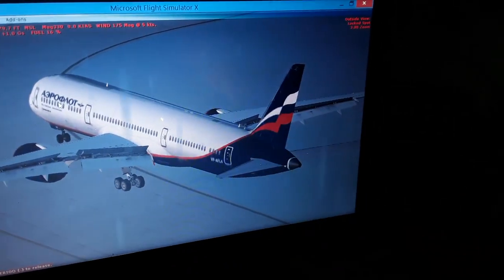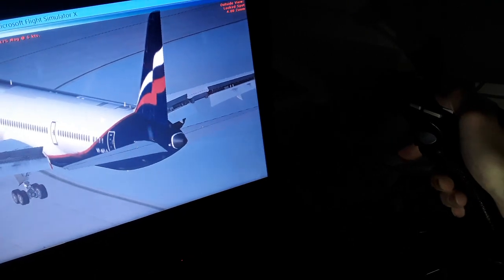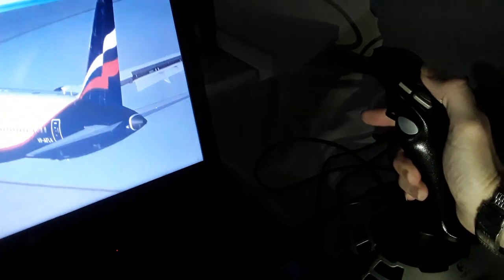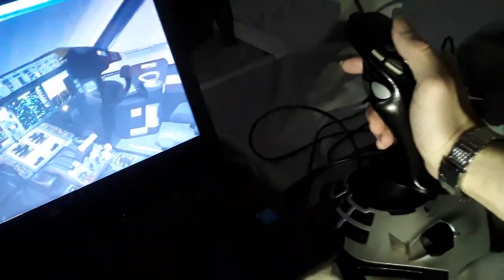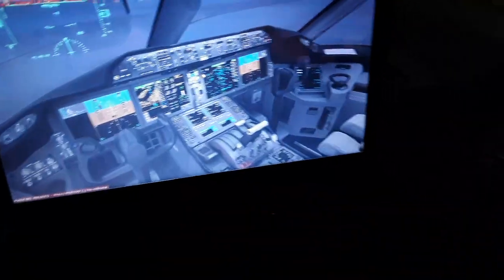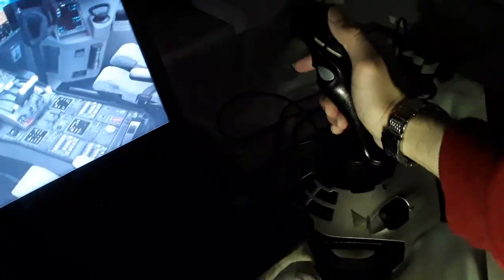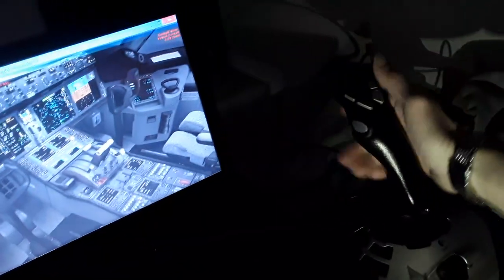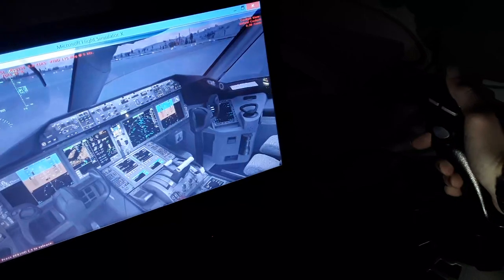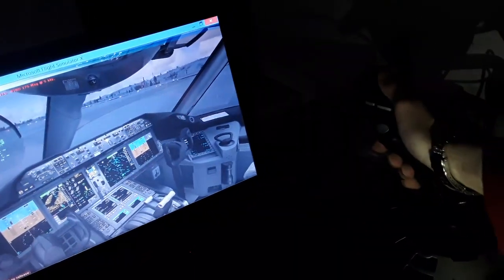So we have here, you can see one more axis, the pitch axis. From wingtip to wingtip we use the joystick in the Airbus for climb and for descent. Take the weight up, climb, take the weight down, descend, like this. So very easy, as you can see. In the Boeing we use the control column, the vertical column of the yoke, to climb and descend instead of the side. You can see the deflection is identical, proportional, the yokes and the side stick when I move it back and forth. Take the weight up, climb, take the weight down, descend.